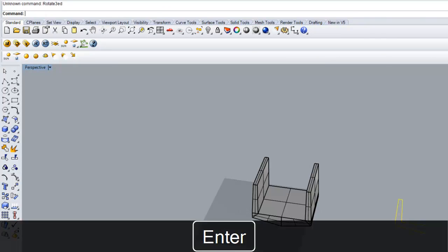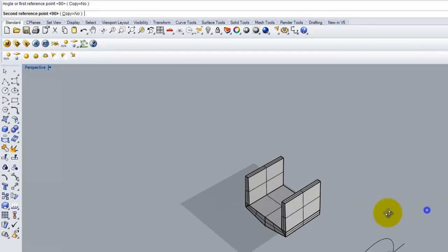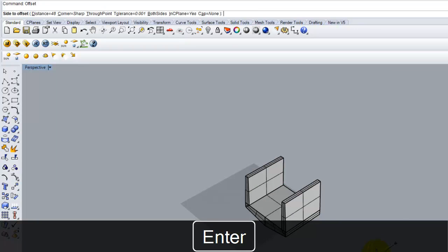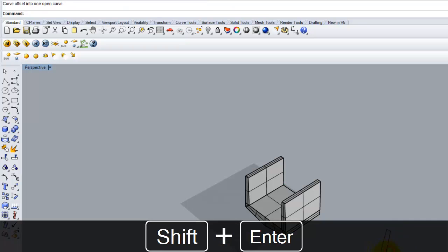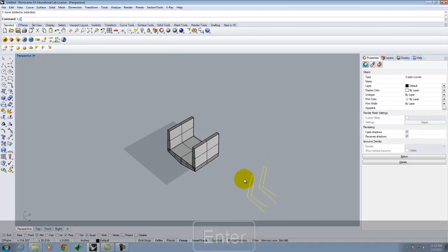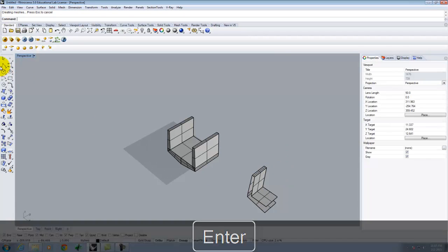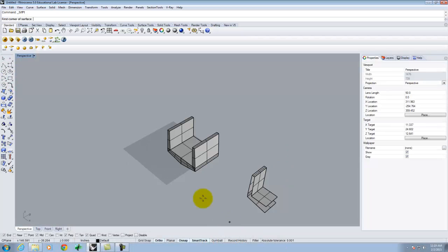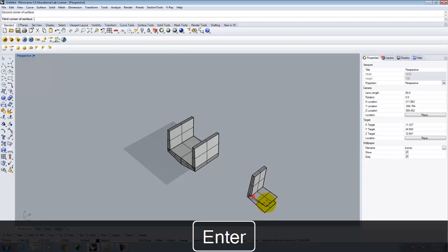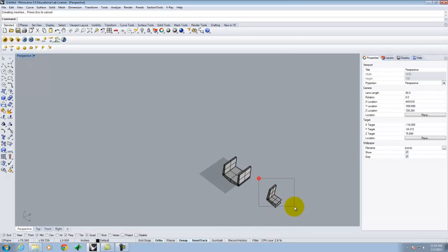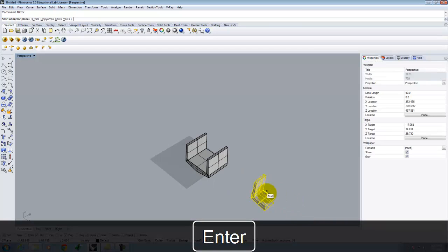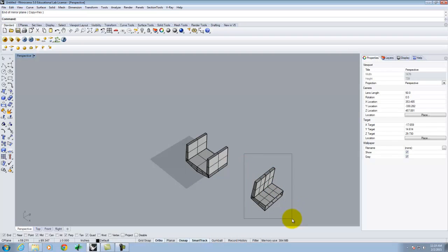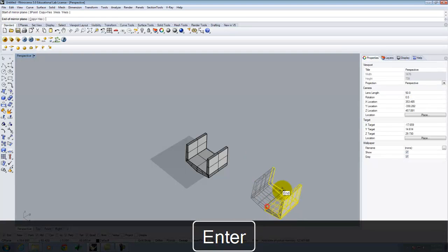Okay, Rotate 3D. Snap it up. Offset 24. So I have just those two, right? Loft. Okay. And then surface from 3 or 4 corner points. And I'll build this out. Like that. Now I have a quarter of it, and so I'm just going to mirror there, and then I'll take the whole thing and I'll mirror there.